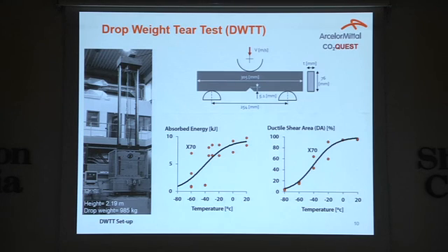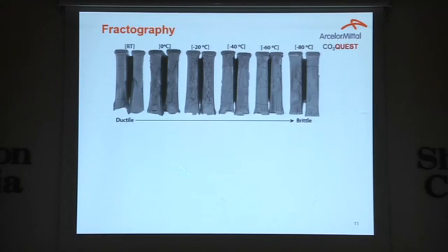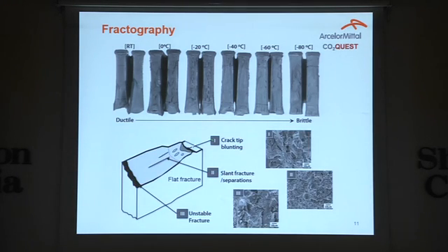But in that case, we can also look into our material fracture surface to see any transition from brittle to ductile fracture, as you can see here. This is a typical ductile behavior, which has a blunting of the crack, it's non-fracture, and at the end we will have a tensile fracture. But if we go to the brittle fracture mode, we see a pure brittle fracture at -80, which is a flat fracture. So in this presentation, we are dealing with this type of fracture.